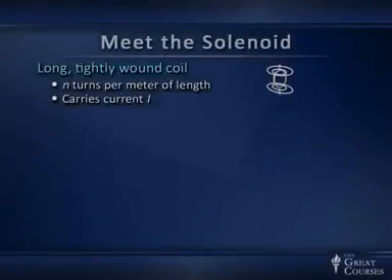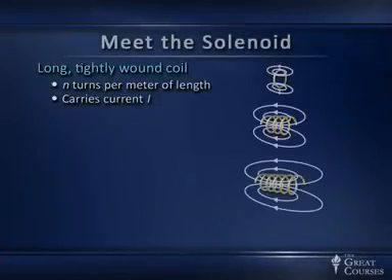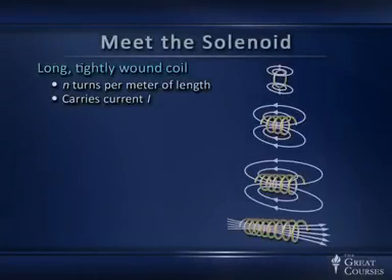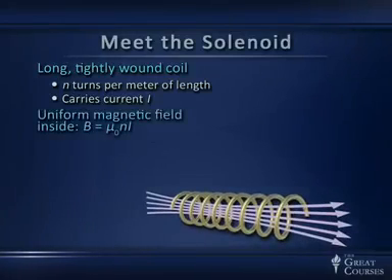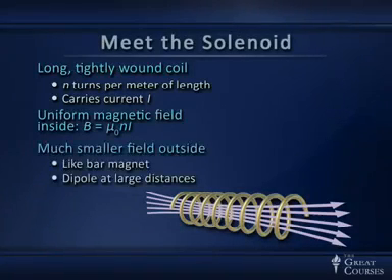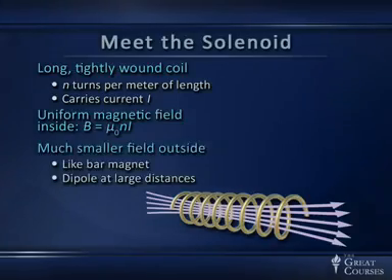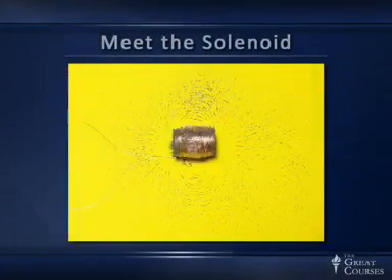It's hollow. And I've shown a picture on the right here where you see a single loop of wire and then several loops and then more loops and finally at the bottom quite a few loops. And when a solenoid gets very long compared to its diameter, the bottommost picture suggests, it develops a magnetic field inside it which is essentially uniform and quite strong, and the field outside is rather weak as those field lines have to converge around on themselves to make that dipole-like looping of the field. Let's take a look at what the field of a solenoid looks like.